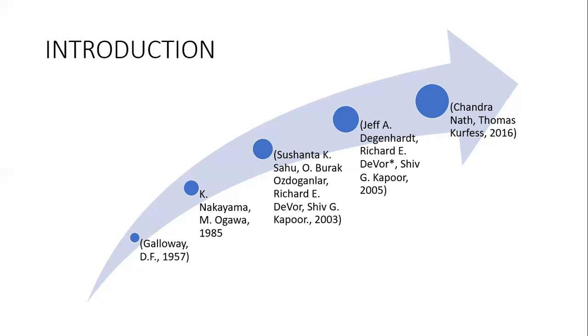The rake design also plays an important role in chip evacuation in the drilling process because it affects chip breaking, said Susanto. Jeff observed that drilling with chip breaker grooves was effective in reducing chip length. Chandra's research showed that there is good potential for the insertion of obstruction pins on the flute space of the drill bit to obtain controllable chips.